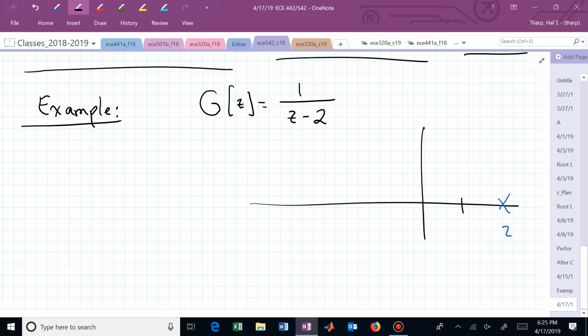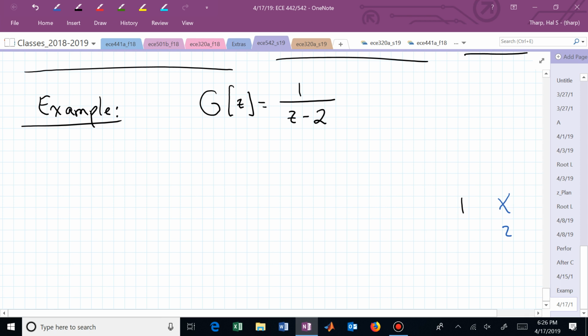But do you see what the root locus of this looks like? For a unity output feedback configuration with just a gain controller, it's going to push that pole inside the unit circle for a certain gain. You have to crank up the gain a little bit to get you inside the unit circle, and not too much to zip you outside -1. But you can stabilize that system with a constant output feedback controller. Now, that's not going to give us the steady state accuracy that we want. So how do we get zero error due to a constant input? What kind of controller is your next choice?